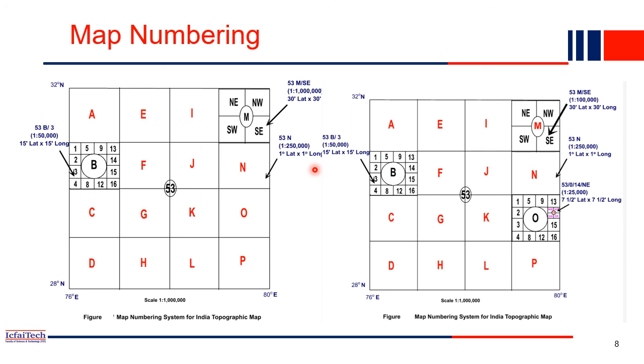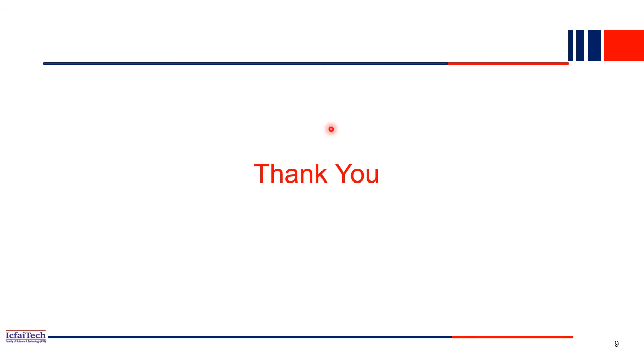What we have understood in this lecture is how exactly field surveying happens. Let me quickly recapitulate. We have the entire area, and we know the control points, meaning we know the latitude and longitude of these 2 points. From there we establish a third point, which is visible from both points. Once we find the latitude and longitude of the new point,